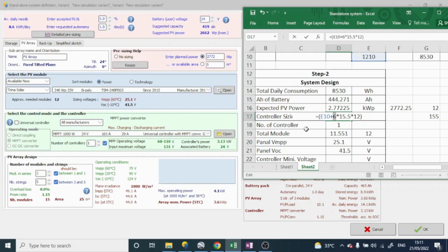It means that with all equipment running at the same time, plus all the batteries charging at the same time, what is the maximum wattage handled by the controller? It should be this much wattage, that is 2326 watts, at the same time. By chance if we are switching on each and every equipment at our home, plus charging the batteries, then the controller should not trip in that situation. That is why we have to be careful whenever we select the controller size. So that is the wattage handled plus 6 batteries charging at the same time.